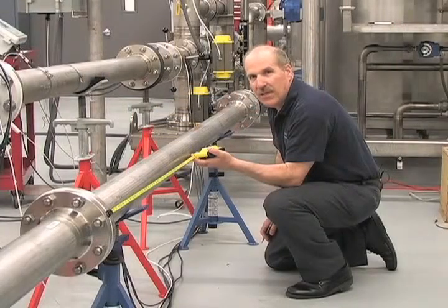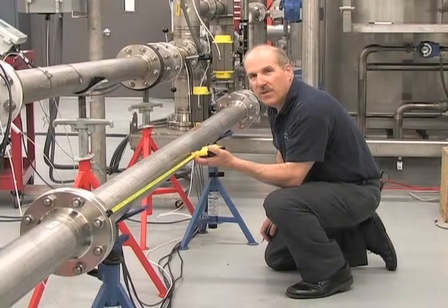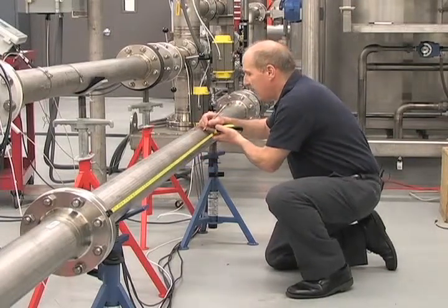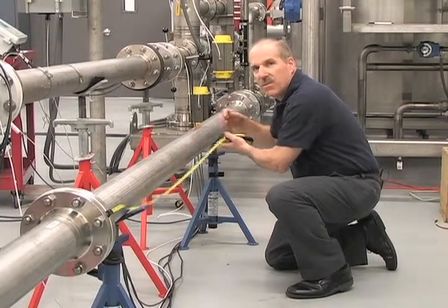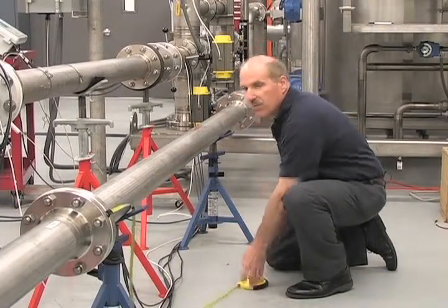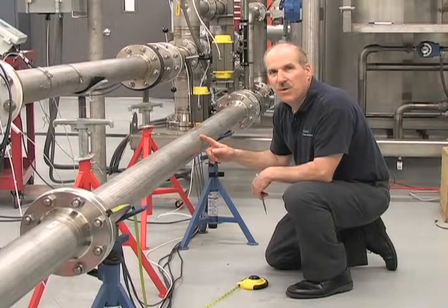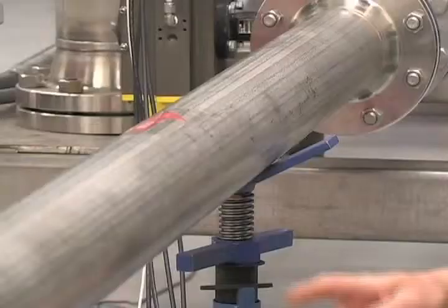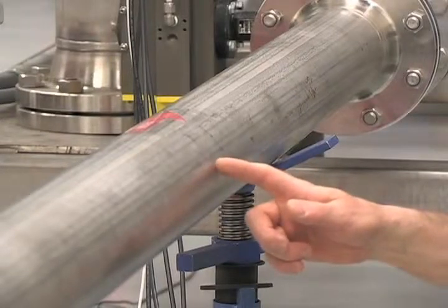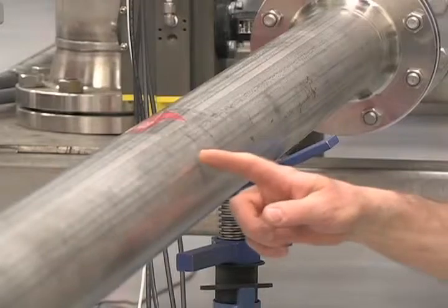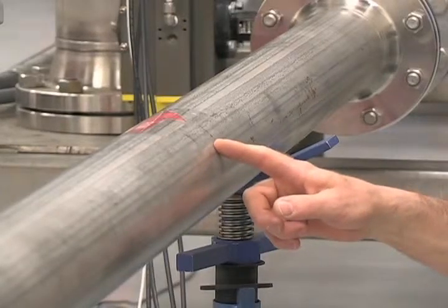Mount the sensors at a location where the flow of liquid is fully developed. As a minimum, use 10 diameters of straight pipe length upstream of the sensor mounting position. The pipe at the sensor mounting location must be full, even at zero flow. The mounting area should be degreased and abraded if there is loose paint or rust. This will give us a clean contact surface for the sensors.